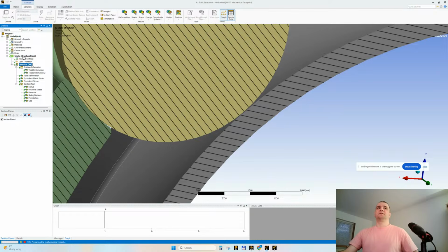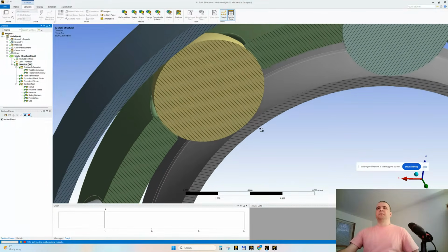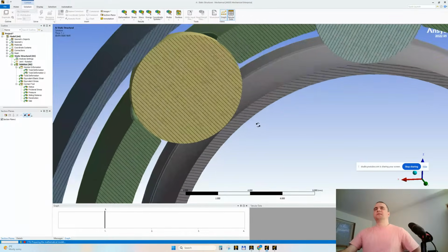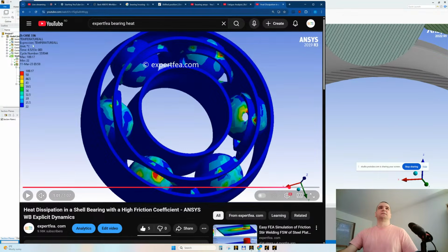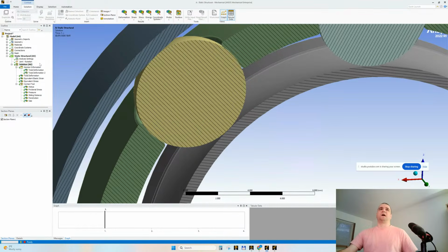In static structural, there is a temperature, it's called BFE. It's called BFE in static structural, but it's pretty complex. So I would say at this moment, in a simple manner, for a beginner, it's not easy to get the dissipated heat. The easiest is in explicit dynamics, okay? And remember, you can access the Temperature All item from the worksheet button, after the solving is made in explicit dynamics, not here, okay?